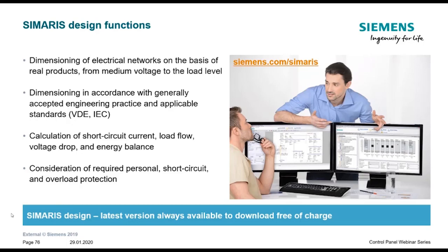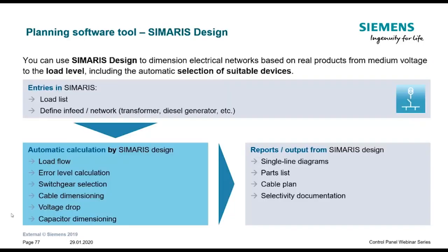Basically, SIMATIC Design is a tool that you use for dimensioning electrical networks on the basis of real products from medium voltage to the load level. You will only need to know the type of load that you're using and the voltages you're connecting them to, and of course the distances. Design will calculate short circuit current, load flow, voltage drop, and energy balance in accordance with the generally accepted engineering practice like IEC standards.